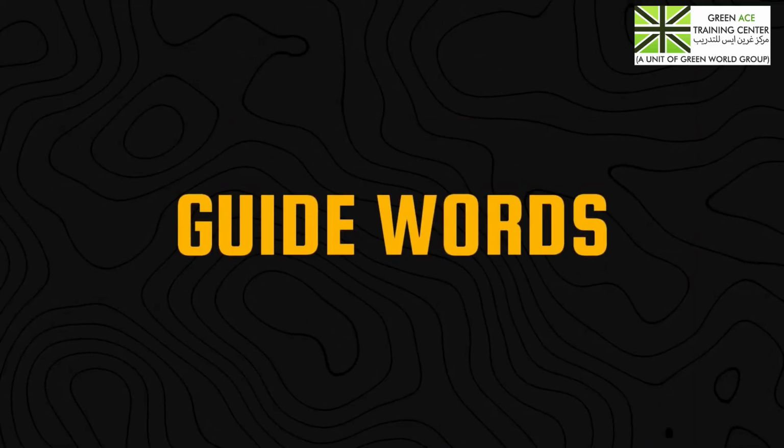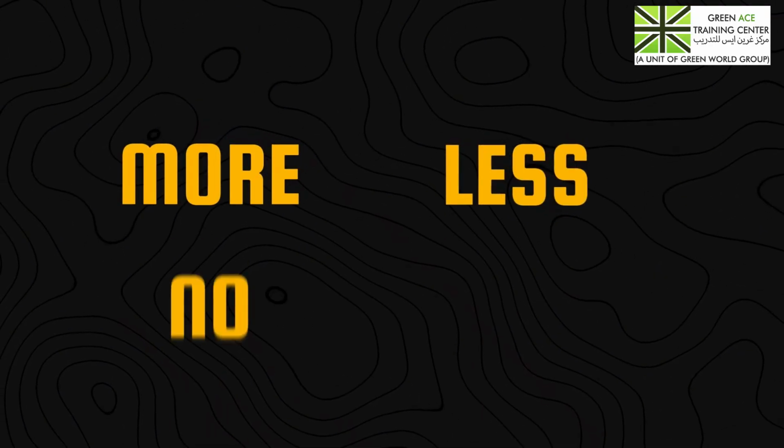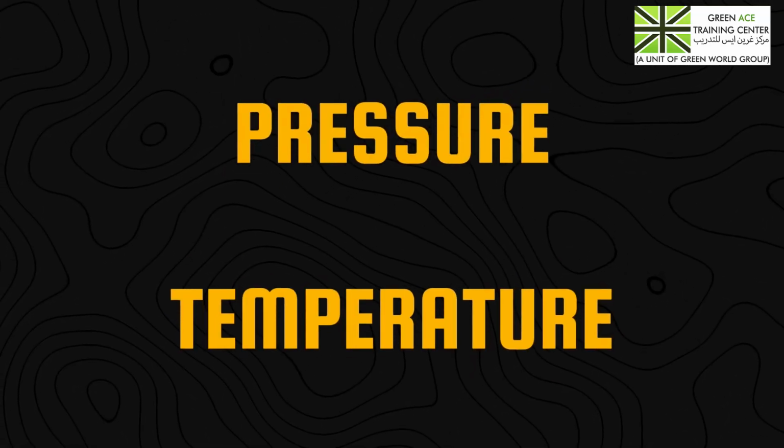And again, what these nodes are and how this is done will be carefully taught to you in a detailed HAZOP training. Now the third important part is the use of guide words. In a HAZOP study, we apply standard guide words like more, less, no, reverse to specify certain process parameters like pressure, temperature, flow, etc. This helps us identify how the processes may deviate from their design intent. For example, what happens if the flow rate of a particular motor is more, or what happens if it is less. That's how we normally do this.